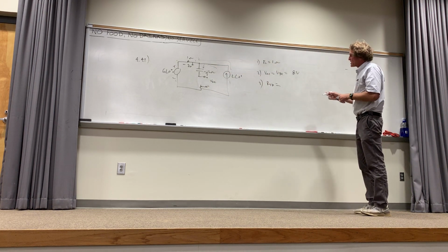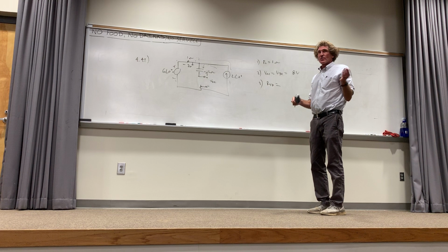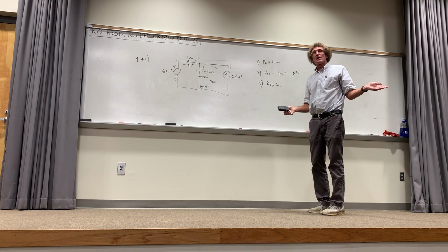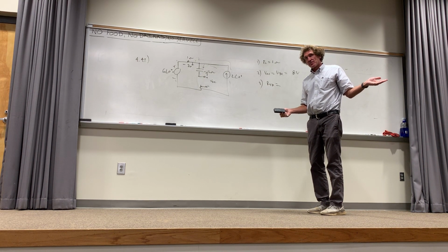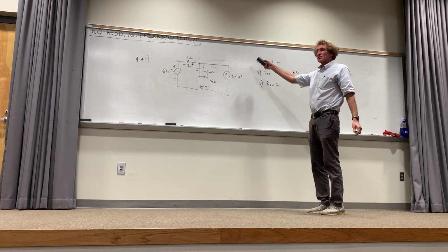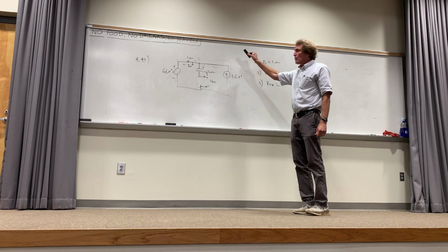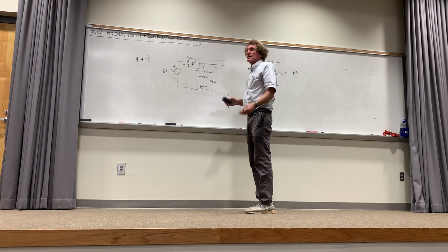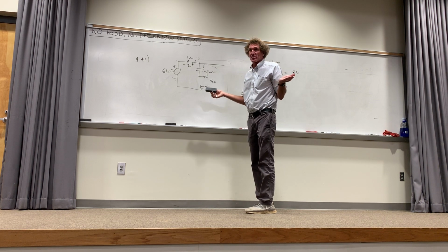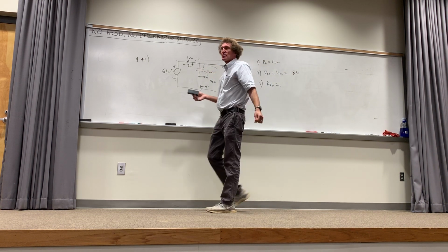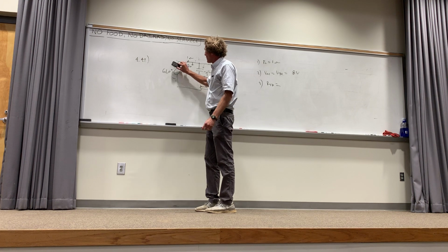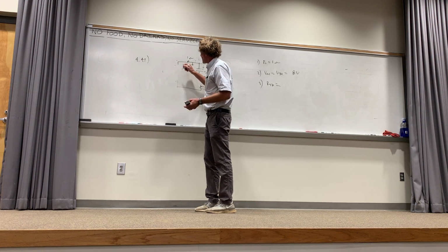Okay, now, what is R Thevenin going to be? First, what do we do with the sources when we want the Thevenin equivalent resistance, class? Turn them off. A current source becomes an open circuit. Just think, if you turn off current, there's no current flowing through, it's an open circuit. When you turn off a voltage source, it goes to 0 volts. It's a straight wire. Follow me?